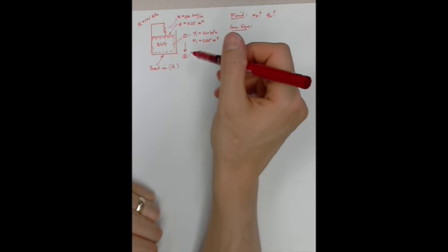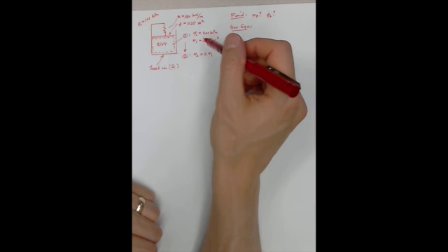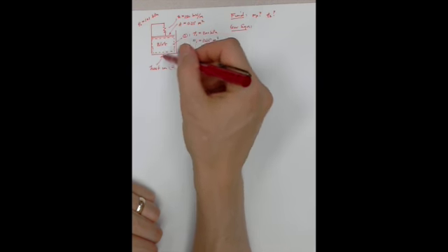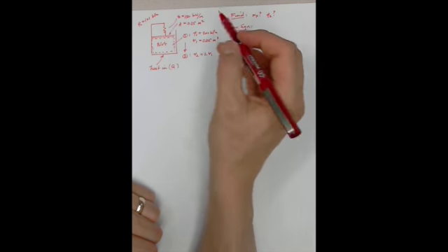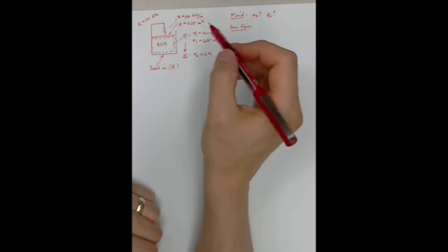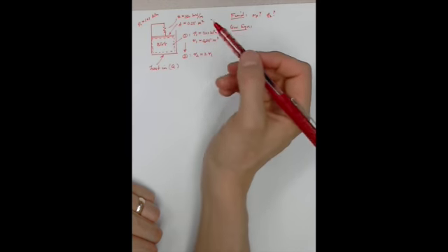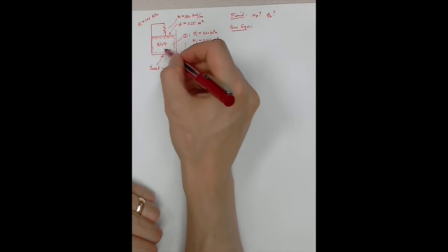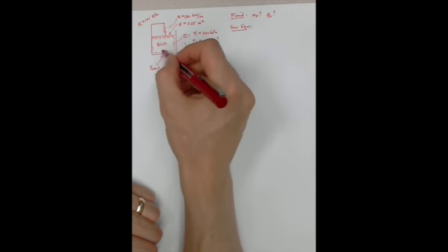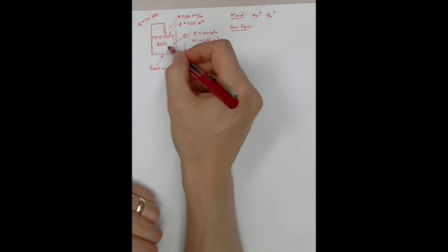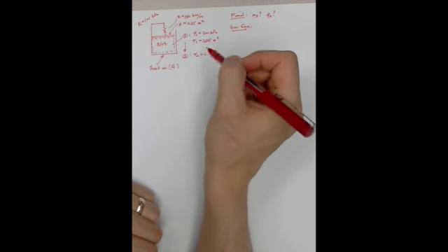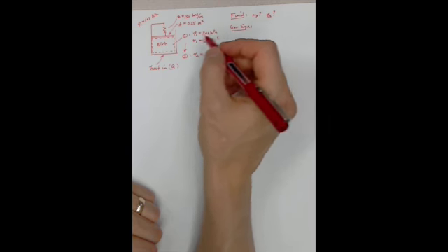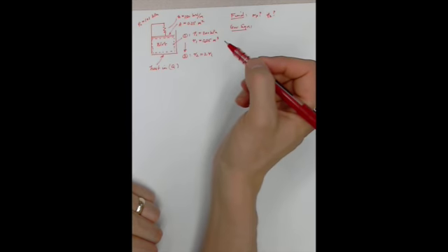The first step would be to reject the ideal gas law. We cannot use the ideal gas law in this problem, even though we have a pressure and a volume given. And the reason for that is that we don't know that this is a gas. So we can't use the ideal gas law unless we know what we're modeling is in fact a gas. This could be a liquid or a mixture of gas and liquid. Secondly, we don't know the substance. So even if we were to assume the ideal gas law, we'd have no way to get our ideal gas constant, which would depend on the substance in this case.